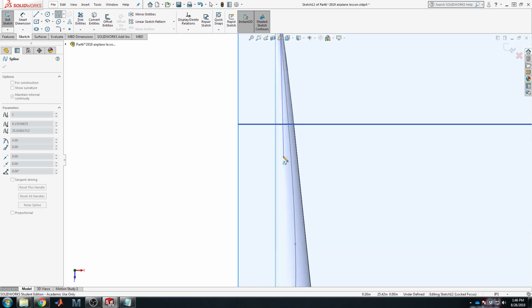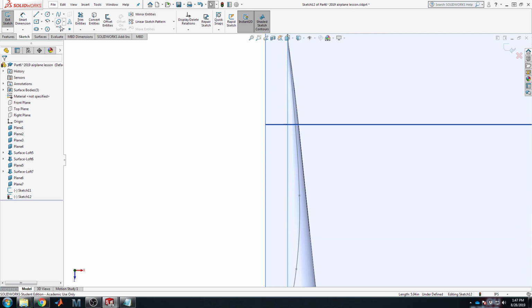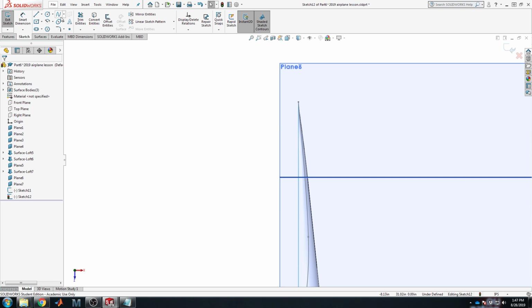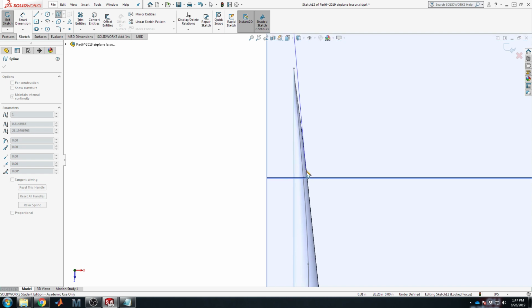So let's see here, going back. Oh, that's annoying. I think, is it Shift or you hold down Shift, Alt, and Control? Yeah, so Shift, Alt, and Control gets rid of all the snapping. You can see it's trying to be nice and help you line things up. That's just at this point being annoying because there's too many things it's trying to snap to. When I'm doing a free-form drawing, well, that's interesting. It just didn't let me continue. Let's try that once more. So Alt's not it by itself. Shift cancels out the operation, so we don't want to do that. Interesting. It used to be all three of them. Maybe, yeah, so now it's just Control by default that eliminates the snap to.